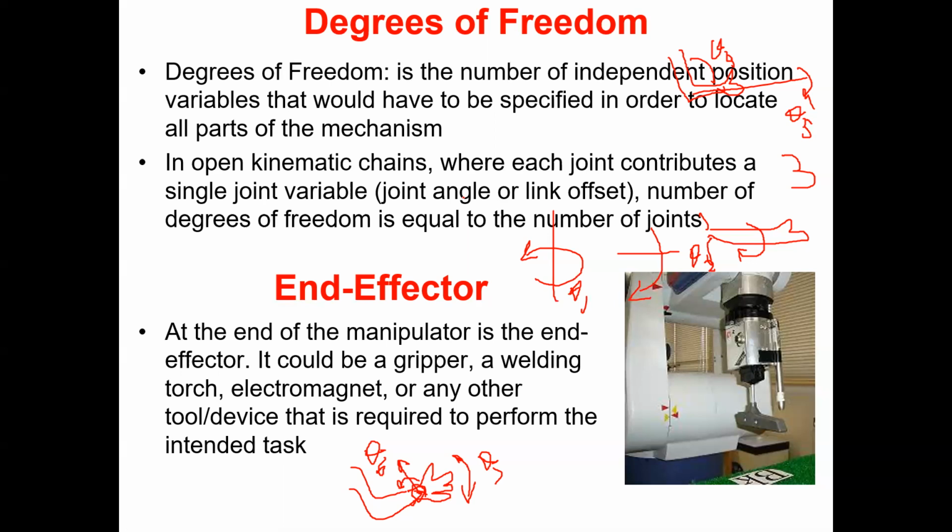And then you get to the final position and orientation. Now, in case of redundant manipulators, you have different angle sets in order to reach the same position and orientation. So if one configuration is not possible for whatever reason, you always can revert to other configurations in order to reach the same position and orientation. So that is the advantage of having more than what is really required in a non-redundant manipulator.